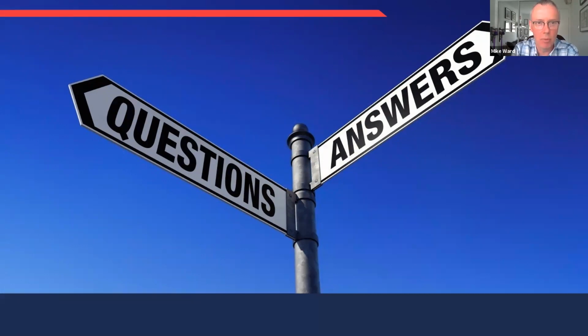So first we have a question from Dan Martin. He said a recent project has had an increase from 60 minutes to 120 minutes. However, it has been identified that HS, I'm assuming, is that high tensile steel in terms of a beam? I guess so, yes. Okay. Hollow section, I think, I've just seen a quick note flash up. Cannot have a thin film intumescent coating applied to meet 120 minutes.